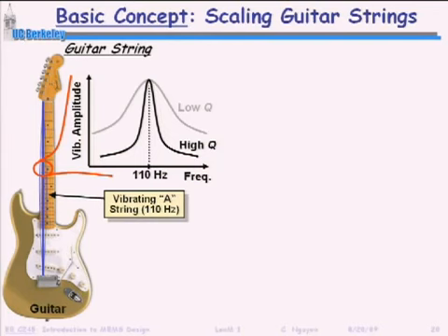So the question is, can we get that 110 hertz to gigahertz? And the answer is absolutely. And you know how it's going to be done. Scaling. Make it smaller. If you make it smaller, fundamentally for mechanics, the frequency at which something vibrates, and everything has a resonance frequency, there's going to be a frequency at which it vibrates. It's all determined by what it's made out of, what its dimensions are. But inevitably, if you make the dimensions smaller and smaller, frequency will go up. And basically, it comes down to stiffness divided by mass, where you could see mass directly in that equation.